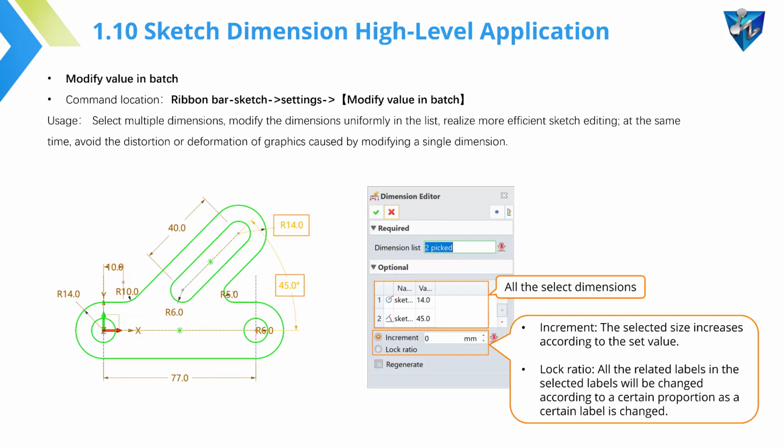The next part I will introduce is another very convenient tool. We call it modify value in batch. This command can also be found under the sketch ribbon tab. So what is modify value in batch?